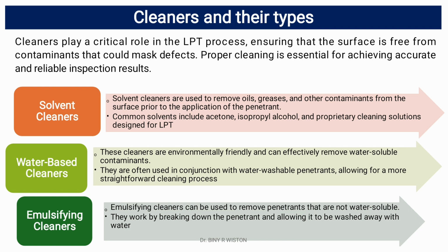Solvent cleaners are used to remove oils, greases and other contaminants from the surface prior to the application of the penetrant. Common solvents used include acetone, isopropyl alcohol and proprietary cleaning solutions designed for LPT.